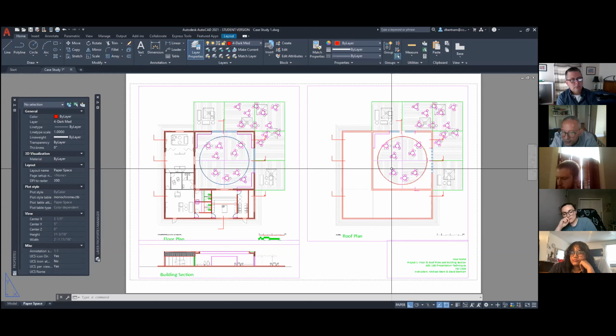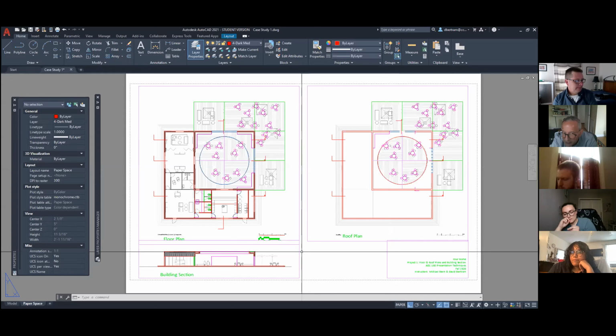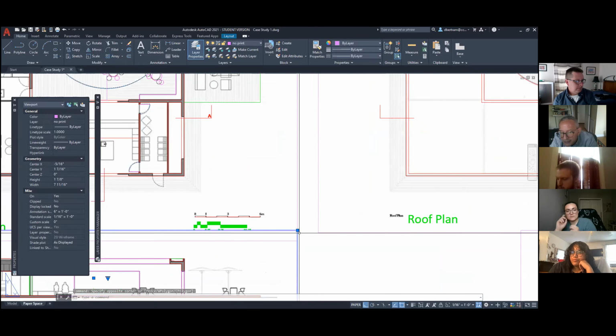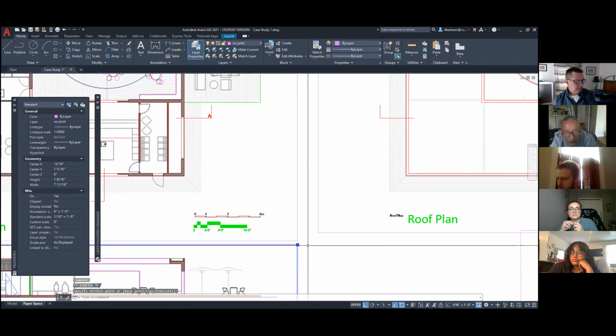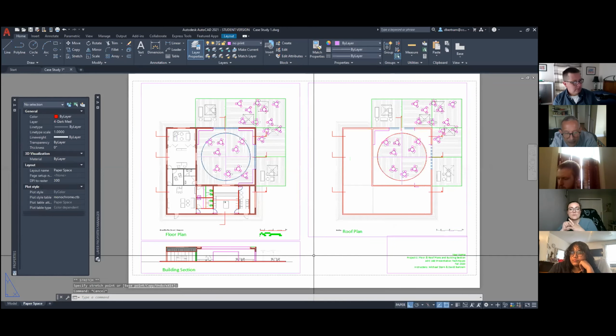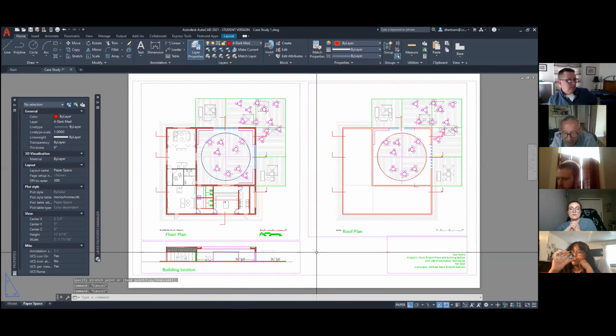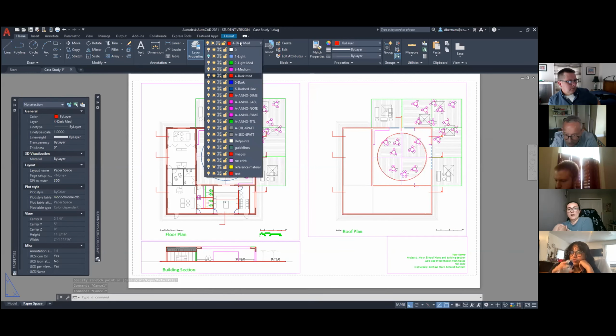And each of these windows, these viewports, are like windows back into model space. So the big thing is keep track of where you are. You should really only be typically in the paper space tab when you're getting ready to print things out. Any drafting you do, for the most part, it's going to be model space.